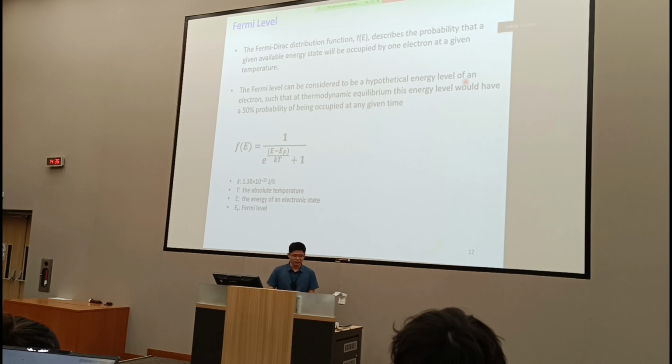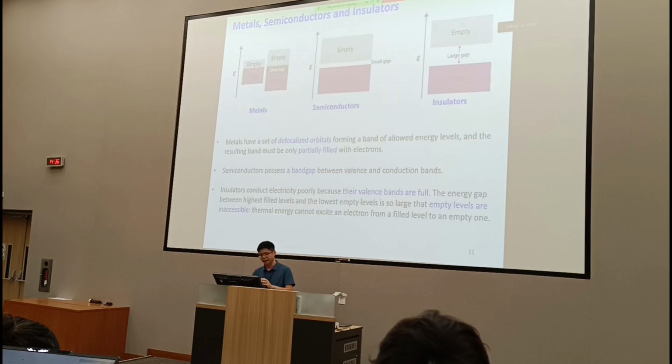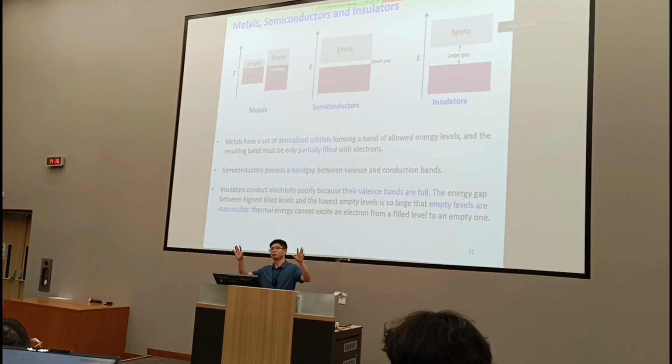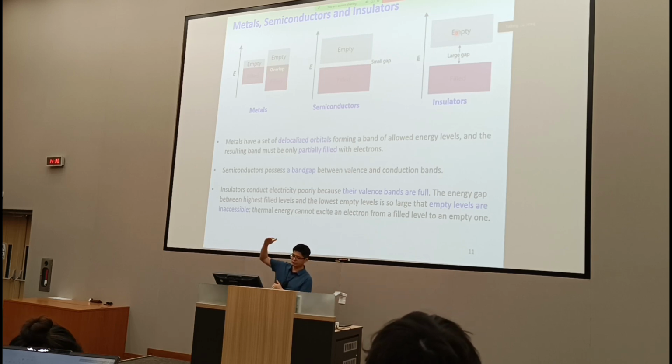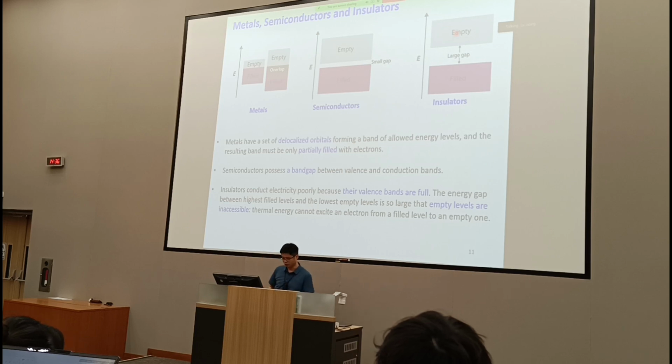Another basic concept is the Fermi level and also the Fermi function. If you look at this simple band diagram, the bottom band, the valence band, is completely filled, and the conduction band is empty. It's similar to simple molecules, where electrons fill from the deep levels up to the HOMO orbital, and then you have the empty LUMO, so there is a HOMO-LUMO gap.